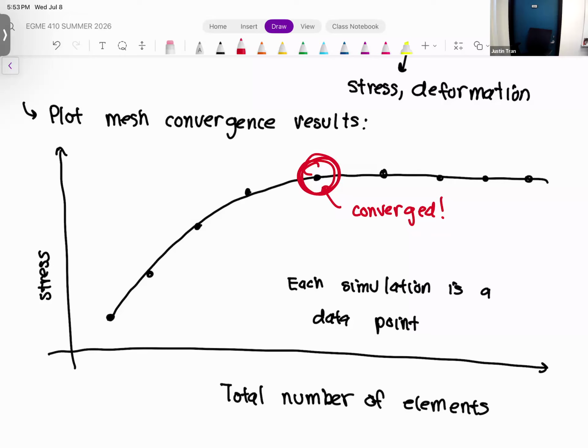And we can fix that by refining our mesh, right? Exactly. Like we did for the first assignment? Exactly. Yeah. So you refine your mesh. Usually an element like this occurs because you have a weird region in your geometry where you can't really fit an element, so it has to stretch. But if you refine the elements there, then if you fill that space with 5 different elements, they're going to be much closer to that shape.